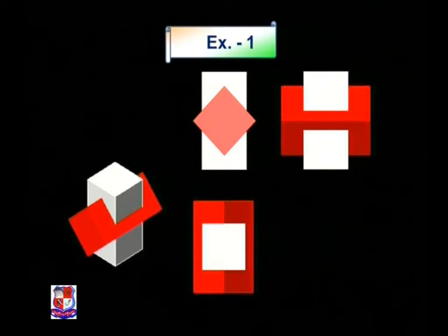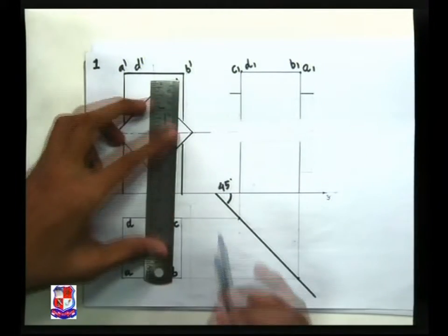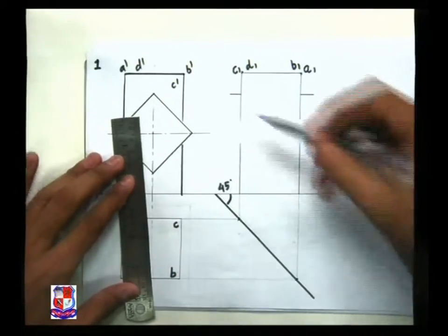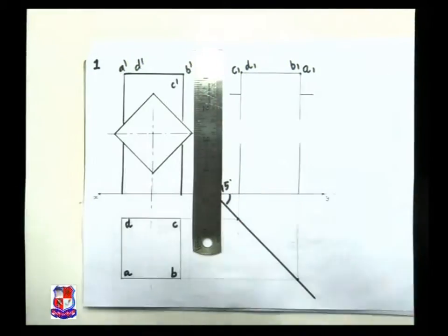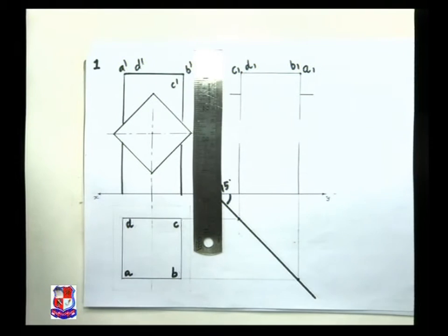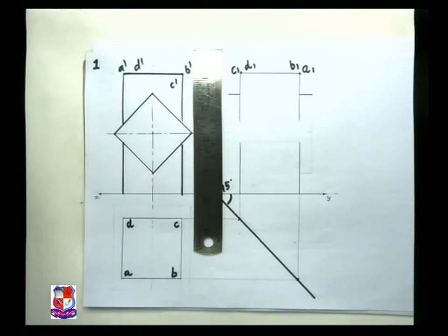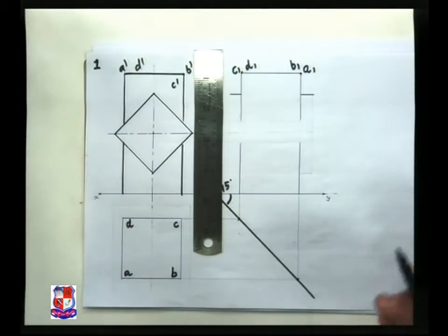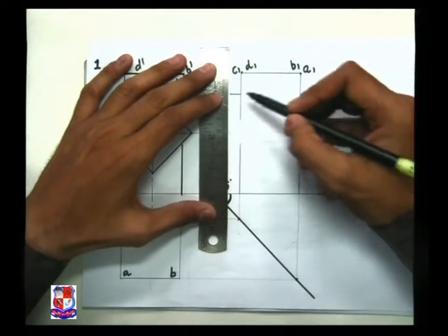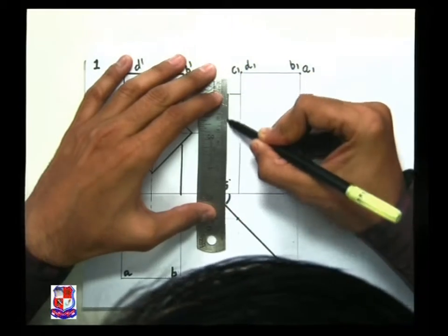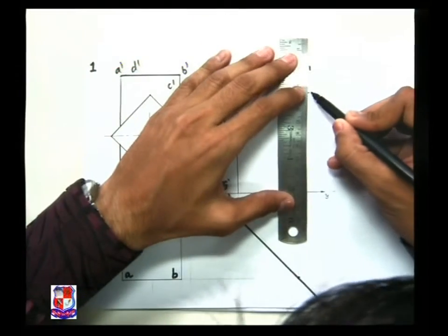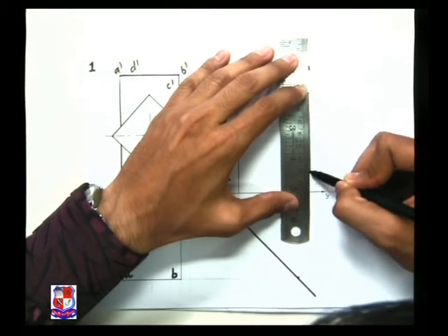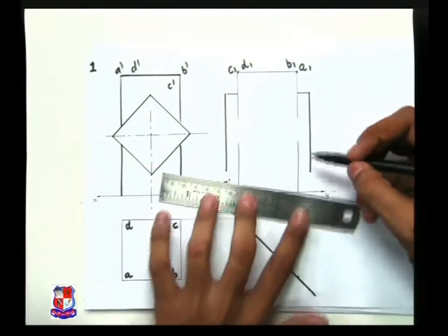Now we think about this shape, how to find out these points, that we will discuss here. Now to find out these points of intersection, let me transfer all these points from here. The length of this solid is given to us, so according to the given length, that is 100 millimeter. So 100 millimeter is the height, or we can, length is not given, so any convenient length could be taken as a reference.